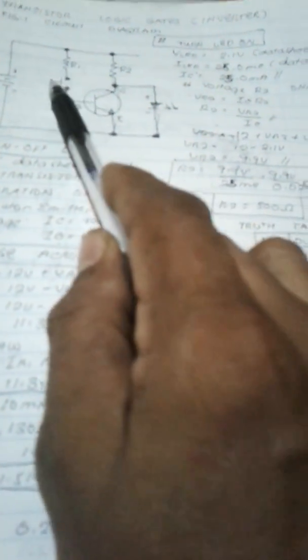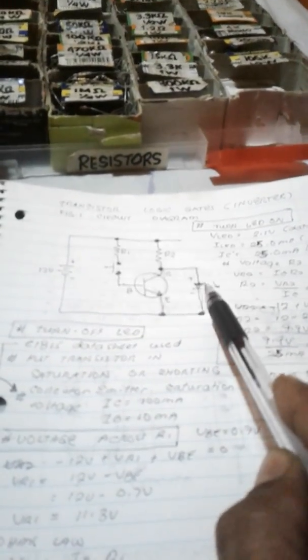Now we have the resistor here, the current flows here. When we push the button, the current goes here and also goes here. Why doesn't the current flow here? Because the voltage drop here is from the data sheet, 2.1 volts. But from the data sheet of the transistor operating in saturation, the voltage drop here is just 0.25.